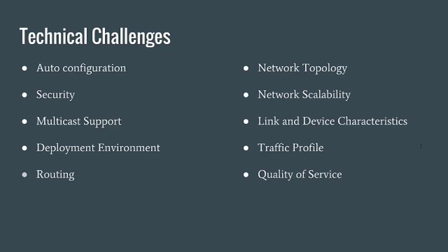The other technical challenges include that the network should be automatically configurable when deployed. Also, to save energy and create a bootstrapping function, multicast routing should be supported in the network. To ensure reliability of data transfer, multiple routing paths should be supported between the source and destination nodes. Also, the routing protocol followed should be aware of the energy levels of sensors and provide balanced energy consumption in the network. The typical network topology followed in an SHM application would be a directed acyclic graph.